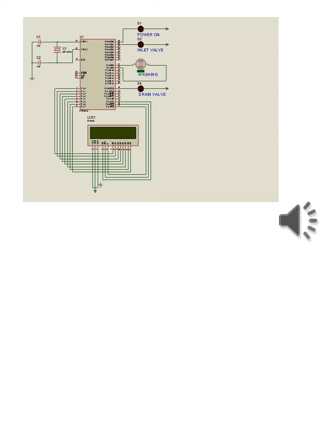We are just going to carry out this operation. In the next slide we are going to explain the program. The program does not have much logic; we are going to set the port and clear the port. In the microcontroller we have a most powerful instruction, the bit handling instruction. So we can set the bit and clear the bit. Each and every port line we can set as well as clear. We have commands, and using those commands we are going to set and clear the ports.